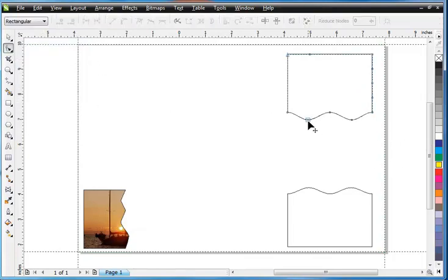Switch to Shape tool and try to move the node. As you can see, the alignment guides are shown only in some specific places, like the middle or the edge of the figure. Let's now try to select and move two nodes at the same time. The alignment guides aren't everywhere, they just show us some specific places in our document.